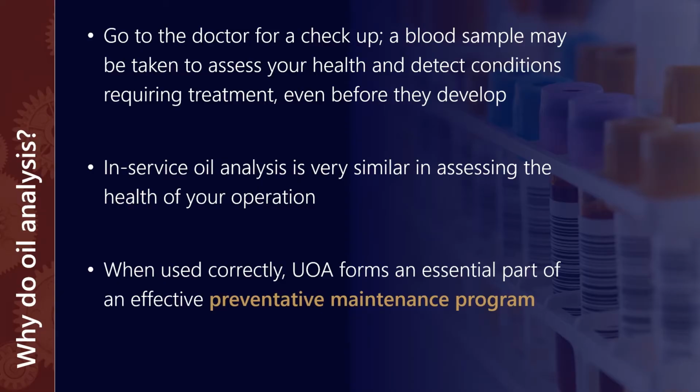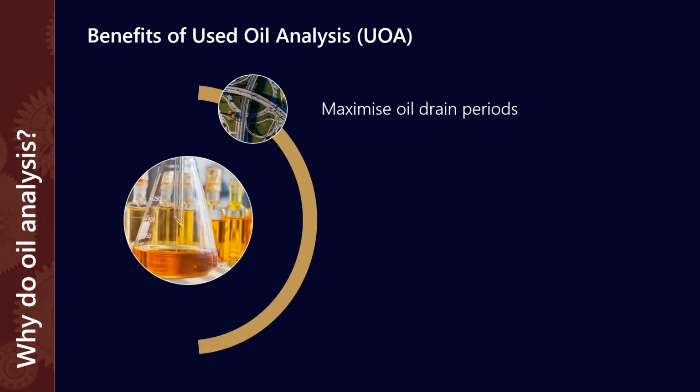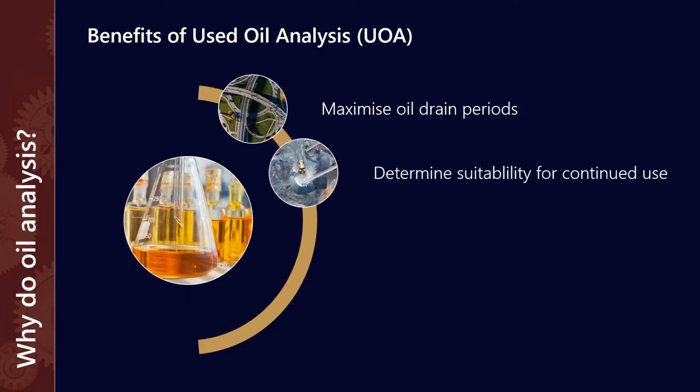Now, used oil analysis is not a panacea, right? It's not the cure-all. It really needs to form just one part of an effective preventative maintenance program. So when we talk about that kind of stuff, what are the benefits? So we can maximize our oil drain periods. We can determine suitability for continued use. So that's, is the lubricant fit for continued service?